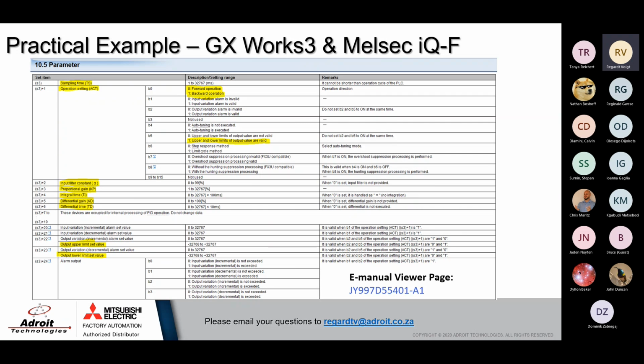If it's none of the above, so if your KP value is reasonably low, and the VFD and pump are not oversized for the tank level, or if it's a very large tank or a very large furnace, or you do temperature control, then the last thing you can look at is whether you use the D factor at all.